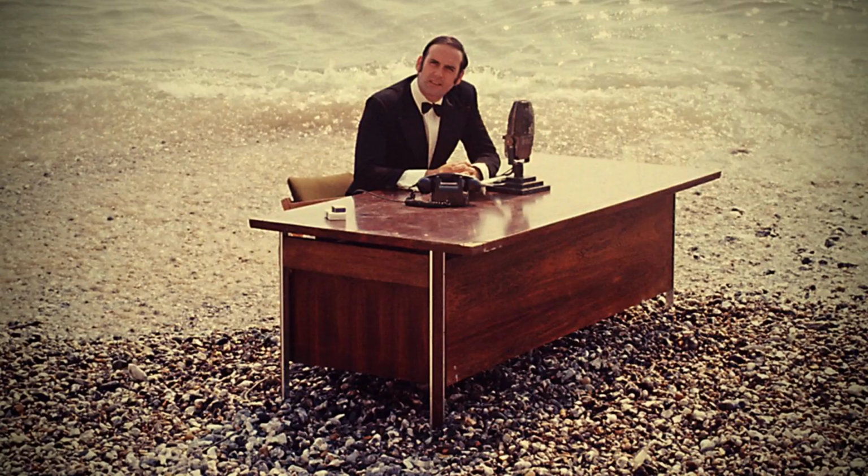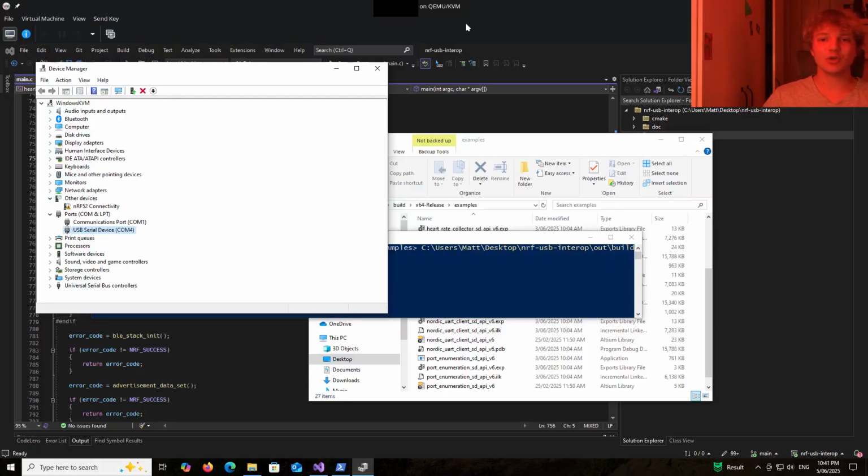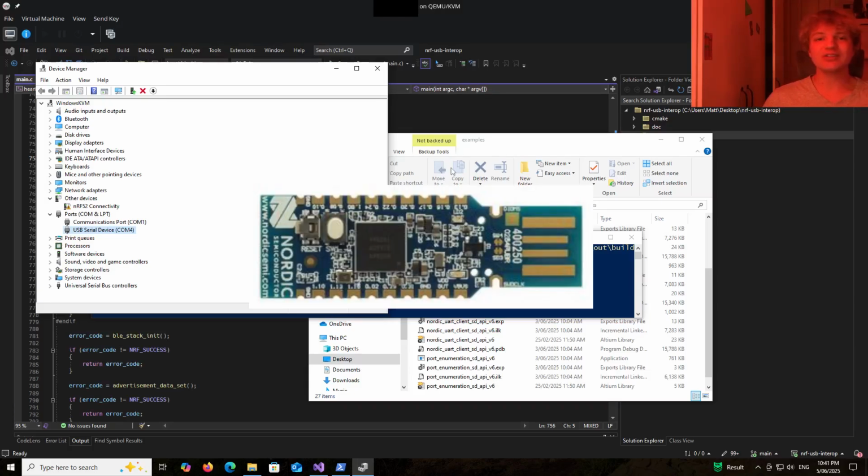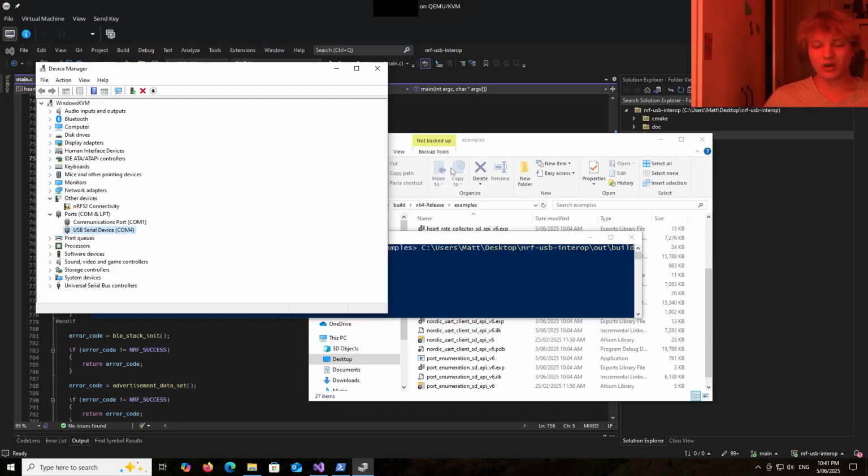And now for something completely different. To demonstrate GATT to you, I'm going to do this on a Windows virtual machine that is actually interacting with a Nordic Semiconductor USB device over UART that it then uses to set up the Bluetooth characteristics. The reason I'm doing this is to show you how varied the Bluetooth APIs are out there, but if you understand the base concepts, you can easily map and figure out what's going on.